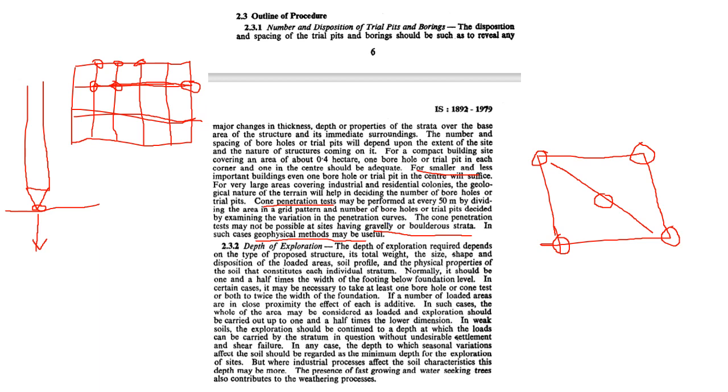Now, another important thing is depth of exploration. Normally it is always ideal to take a borehole up to the hard stratum that you observe at site. As you go on digging into the soil profile, at some point you should be finding a hard stratum.